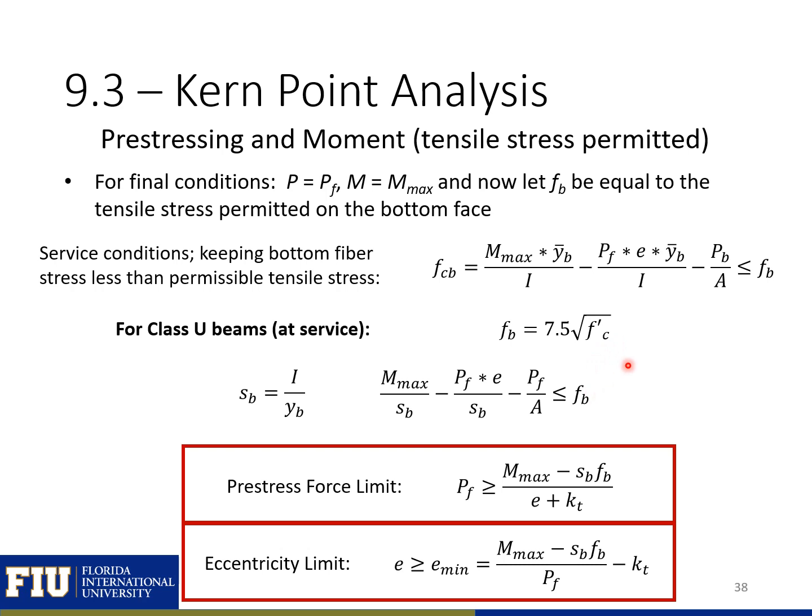So we can solve from this expression. We can solve for either the pre-stress force limit. So come up with the minimum amount of pre-stressing that we can have to satisfy our initial design. And we can also come up with an equation to find the minimum eccentricity of our strands, so E min.